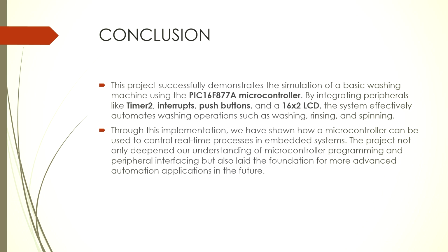Conclusion. Coming to the conclusion part, this project successfully demonstrates the simulation of a basic washing machine using the PIC16F877A microcontroller. As we can see in the demonstration video, we have used the PIC16F877A microcontroller. Along with that, we also have integrated peripherals like the timer, which is an 8-bit timer, and interrupts that are used for button presses as well as for the timer interrupts.